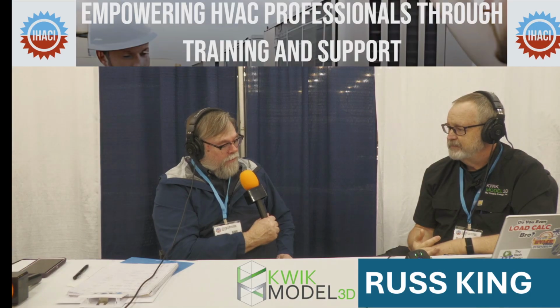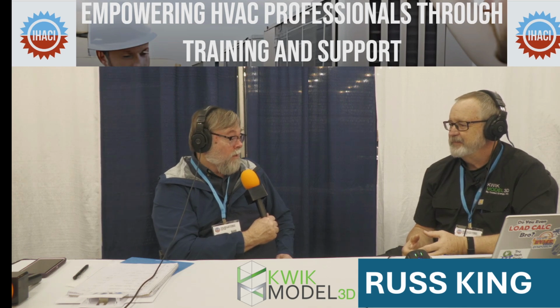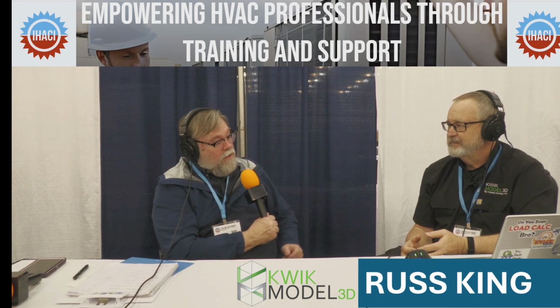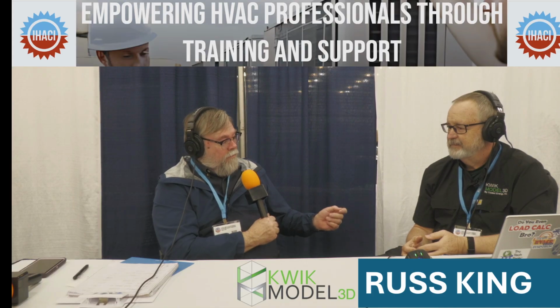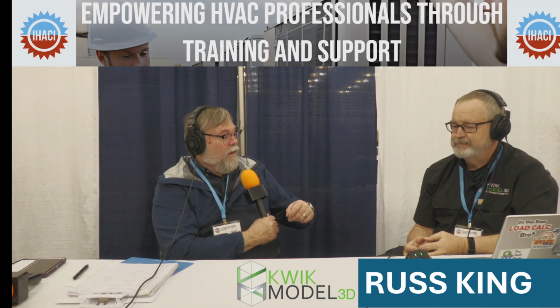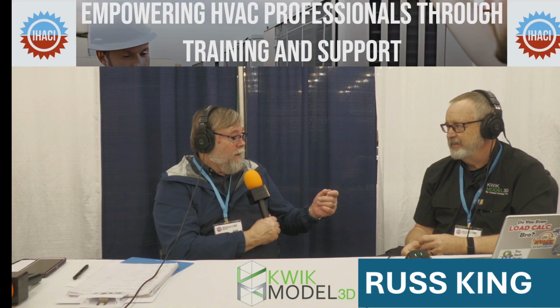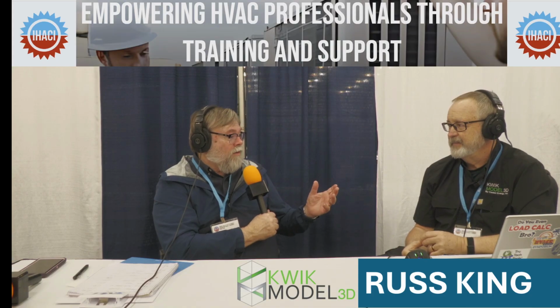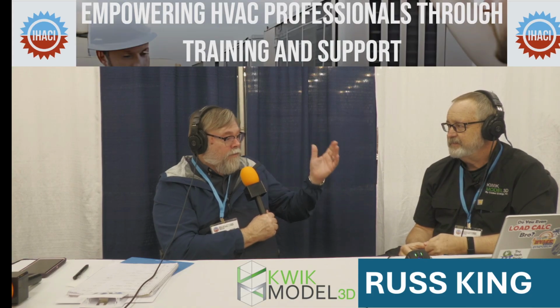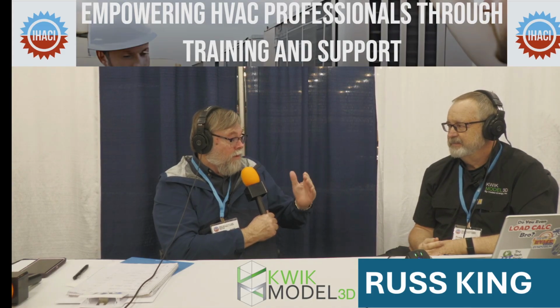Like when I'm doing a customer and I go, okay, let's see. Your infiltration was 5,000 cubic feet per minute at 50, and your house is only 2,000 square feet. That's a lot of air changes per hour. But what if we reduce that in half? What if we went from R19 to R60? What if we did sunscreens on the house? And it's amazing how we can drop the tonnage down from like a 3.5 ton down to a 3 ton or less.